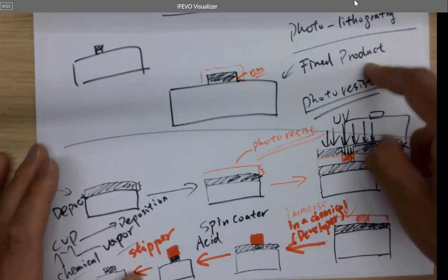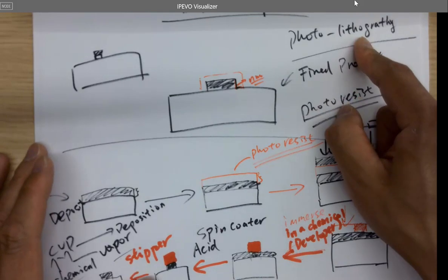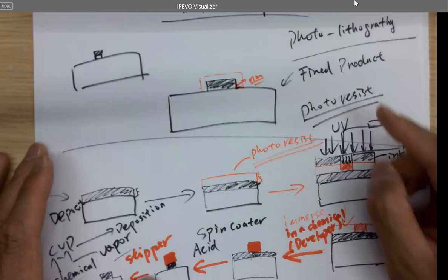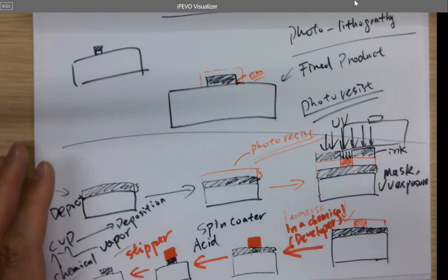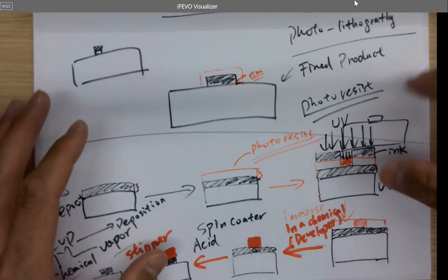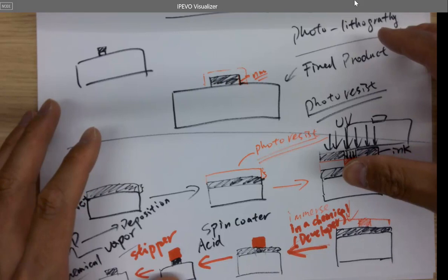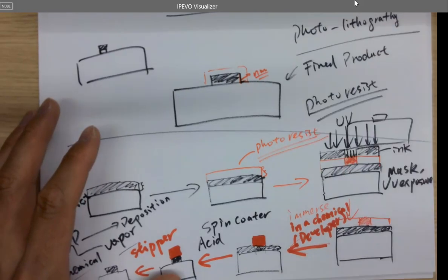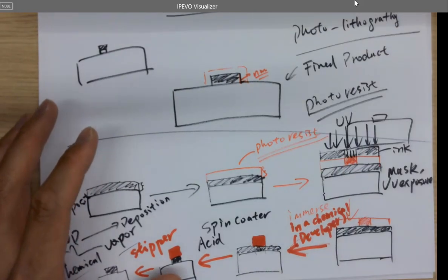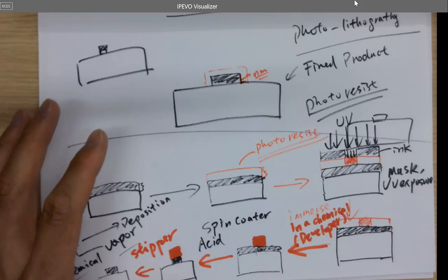So photolithography can give you nanometer resolution. For the photolithography equipment we have in the lab, we can make down to 1 micron. But for the e-beam lithography of the SEM on the 3rd floor lab of Dr. Jessings, I can probably make a dot down to 50 nanometers, I think.